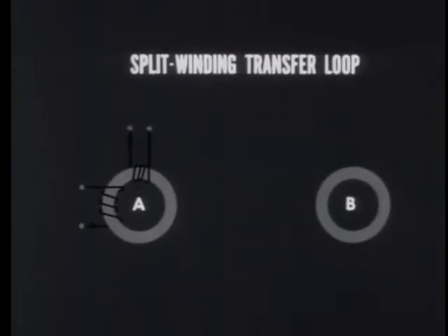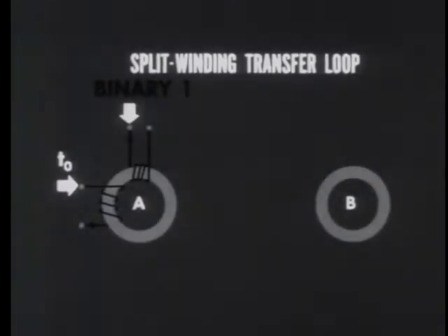We'll add two input windings first. The input on the left is connected so that the current flows into it on the non-dot side only. This is the one that our logical diagram showed as coming in at time t0 and setting core A to binary 1. At the top, current comes in on the dot side, setting core A to binary 0, and the time is t1.